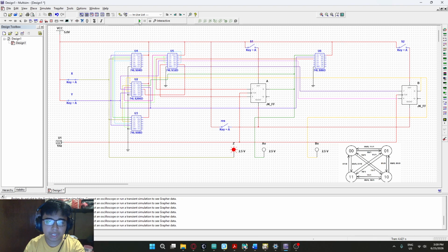Now let's say that we change the inputs in the middle of the run. Let's say for now we have 1, 0 here. Let's say we change the input to 0, 1, which would invert it. We currently have a state of 1, 0, and if we place the inputs at 0, 1, it would invert this current state into 0, 1 as well. So as you can see, Z was turned off because it is no longer a prime, and then the state was inverted into 0, 1.